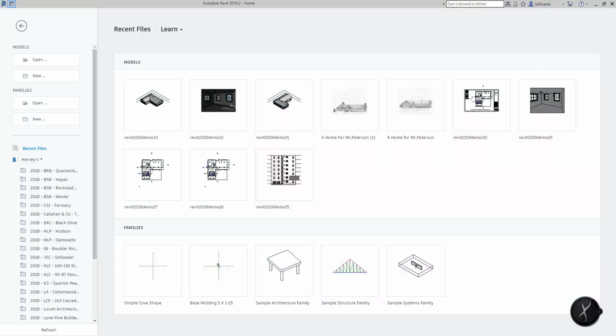So we're going to create and set a reference to level 1. So we're going to create, and then we're going to set level 1, reference level, and hit OK. And then from there, we want to create a blend. So we're going to create a blend and make a rectangle. And what we're going to do is we're going to draw the rectangle within this inner length. And I'm going to lock each one of these values to that internal base. And now I want the depth to be 1 foot. And I want the top offset to be 3 inches, which I don't have at this point. So for now, we have that set correctly, and I want the offset to be 3 inches. So that's editing the top of that.